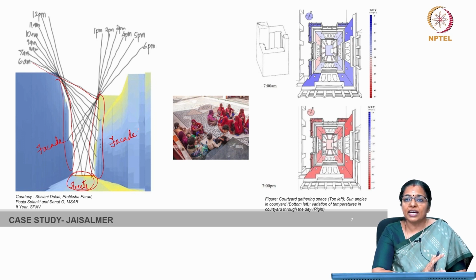Small projections can effectively provide shade during this period. Conversely, the north face of buildings on the opposite side of the streets receive radiation before 8 am and after 4 pm, with a solar altitude of less than 35 degrees. So, buildings on the opposite streets play a role in shading the north face during these times.